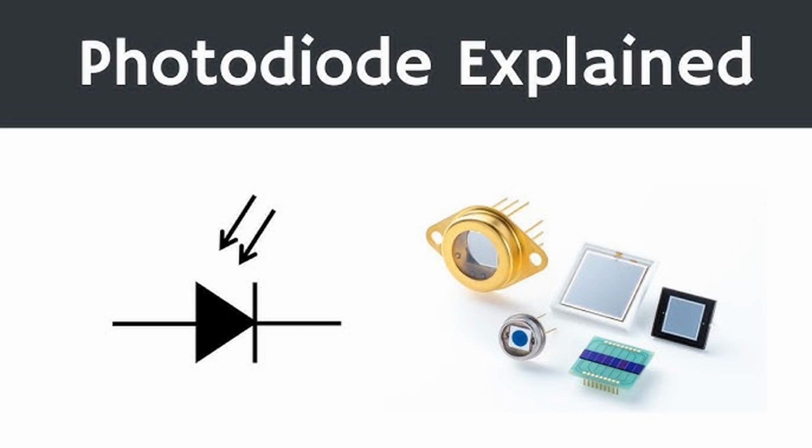3. Noise equivalent power, NEP. Definition. NEP is the amount of light power that produces a signal equal to the noise level of the system. It is measured in watts per square root hertz, W/√Hz. Lower NEP. A lower NEP means the photodiode can detect weaker signals with less noise, making it more sensitive. Relation to dark current. A photodiode with lower dark current will typically have a lower NEP.